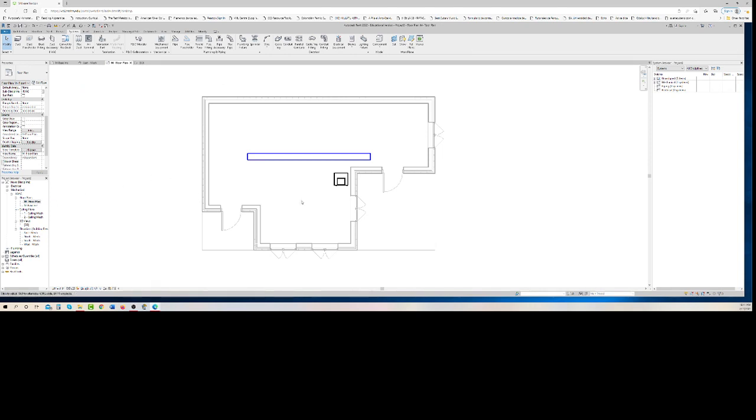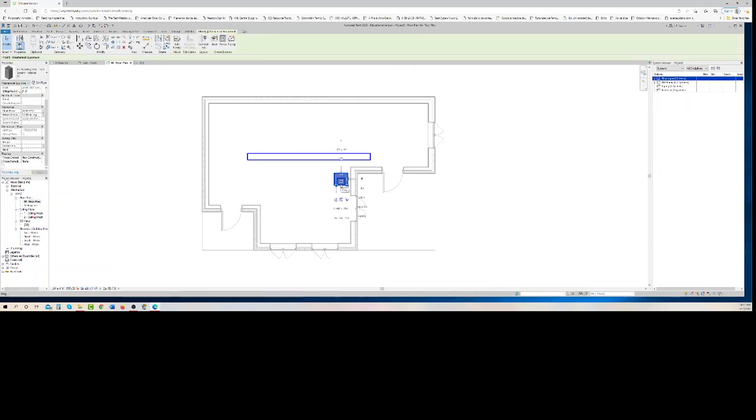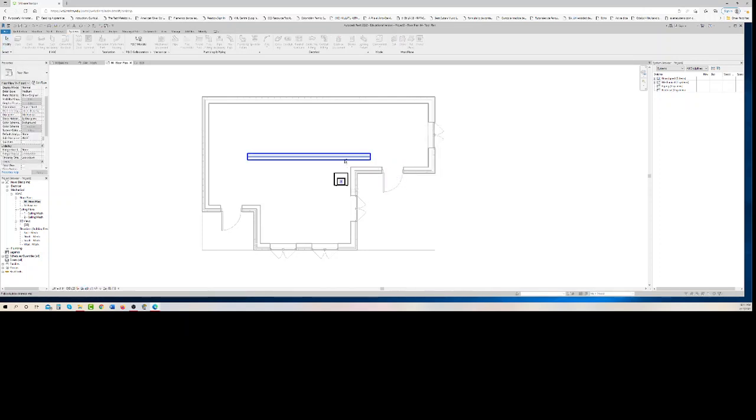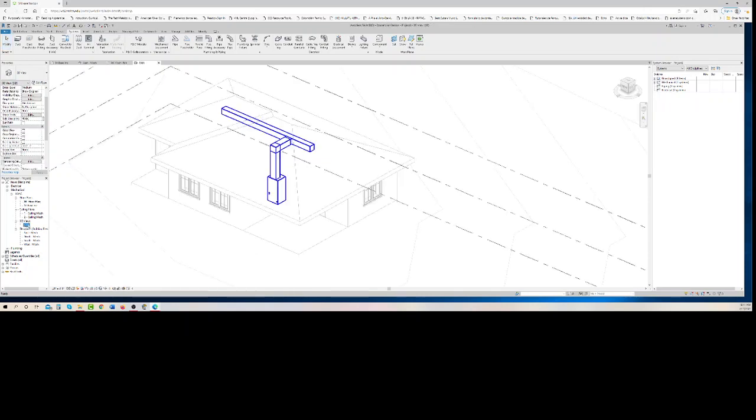Here's a really cool thing. If I click on the air handler, I know that it's going to have to connect into something. That's what air handlers do. They connect into the ducting. So I'm going to say connect into supply air, out. Yep, I want the out. And then click onto there. And that's my whole next step. Place the air handler, place the duct, connect the duct. And when we see it in 3D, it should look something kind of like that.